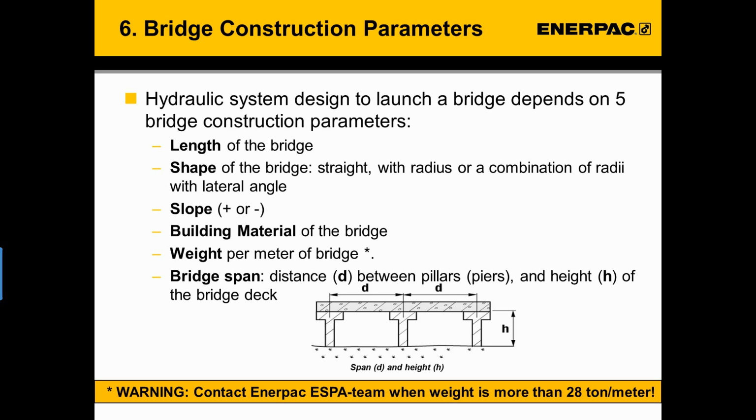Important to know is that when the weight is more than 28 metric tons per meter, always contact the Enerpac ESPA organization for correct solution considerations. And then of course there is the bridge span, the distance, indicated with D, between the pillars or piers, and the height, indicated with H, of the bridge deck.